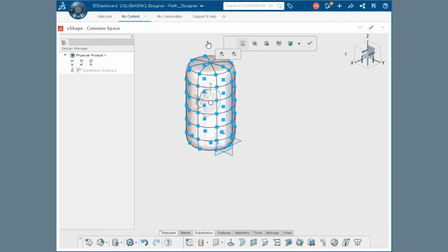Why does it remain selected? At this time, the entire primitive can be moved, rotated, or scaled using the handles in any of the three directions. If you are satisfied with the position, orientation, and size, simply click off of the geometry to deselect it. Although nothing is selected, the primitive remains active and can be edited until the OK button is pressed. Note that only one primitive sub-D surface can be active for editing at a time.